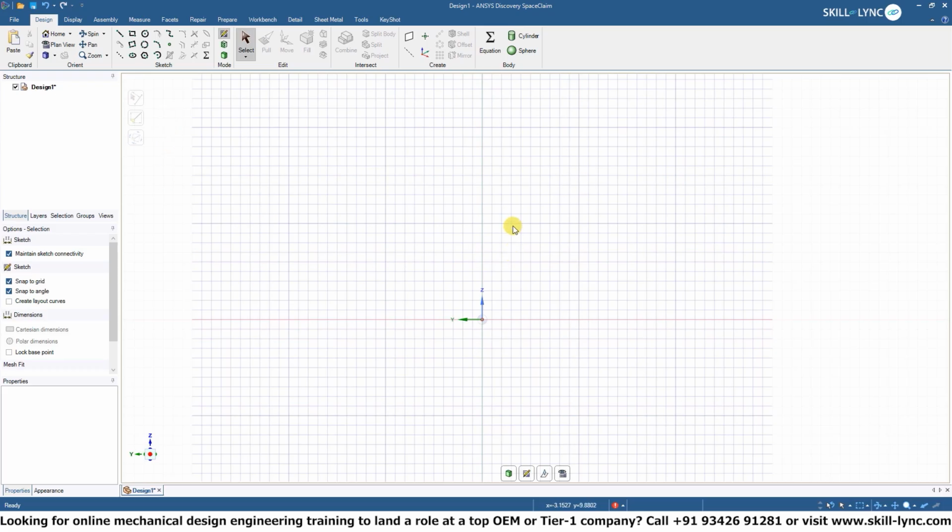But please try to focus on the main tools, which are the line tool, the circle tool, the 2-point rectangle, and how you can use construction lines when you want to do a pull sweep or pull rotation. Try to practice with the normal pull tool.